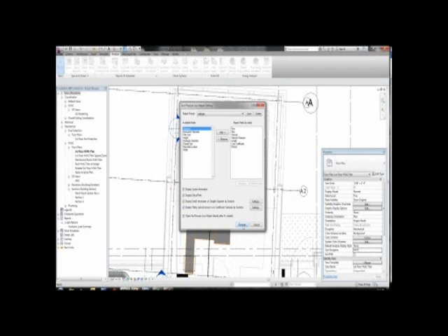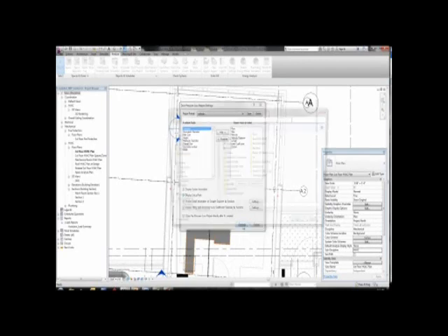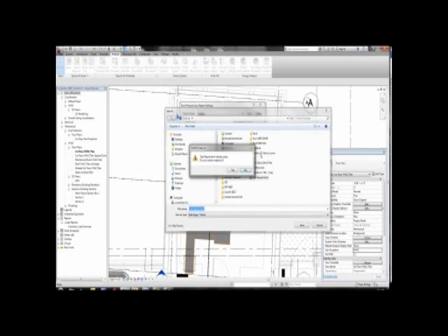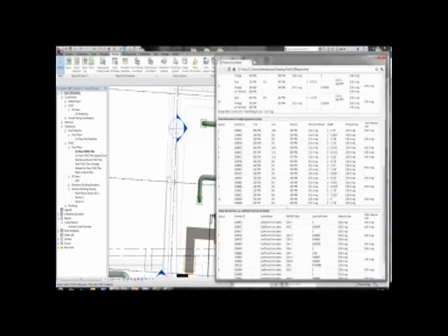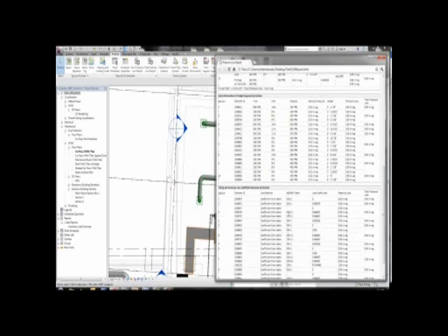Right, and we can see as it generates that pressure loss report, it gives me the information for the project and for the specific fan coil unit that I'm using. And now you can start seeing all the information coming out of the elements, especially velocities and velocity pressures, based upon those certain lengths. And we'll also have the detailed information of straight segments in the section. So it's giving me, again, the velocity, the flow, the size, and the fittings and accessory loss coefficient summary by section, which is now based off that ASHRAE table.